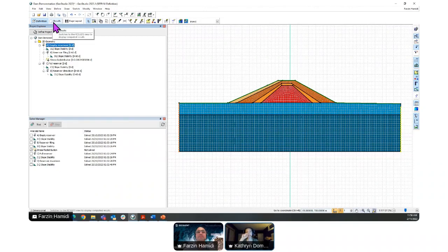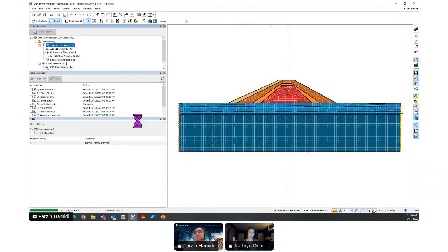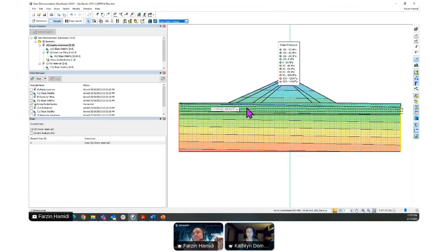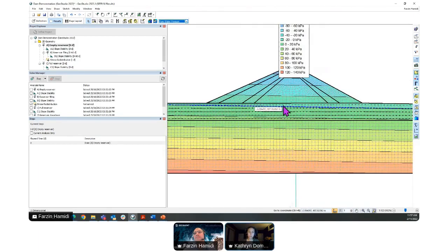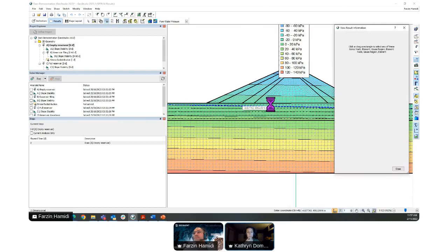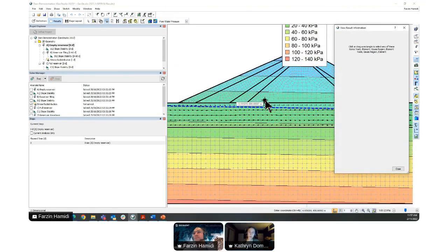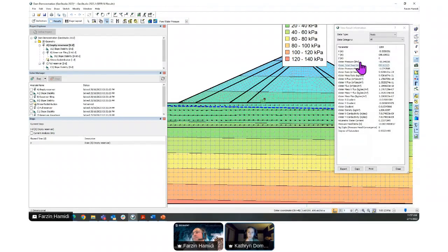And then it becomes that more gradual change to the water level in a hydrostatic system where you then go down to the water level and get a pore water pressure value of 0. Or I should say you should go up. You increase to a 0 pore water pressure level. So what I would suggest doing, if you're in that unsaturated zone and you don't know where the water level is, is you can use an activation pore water pressure value.